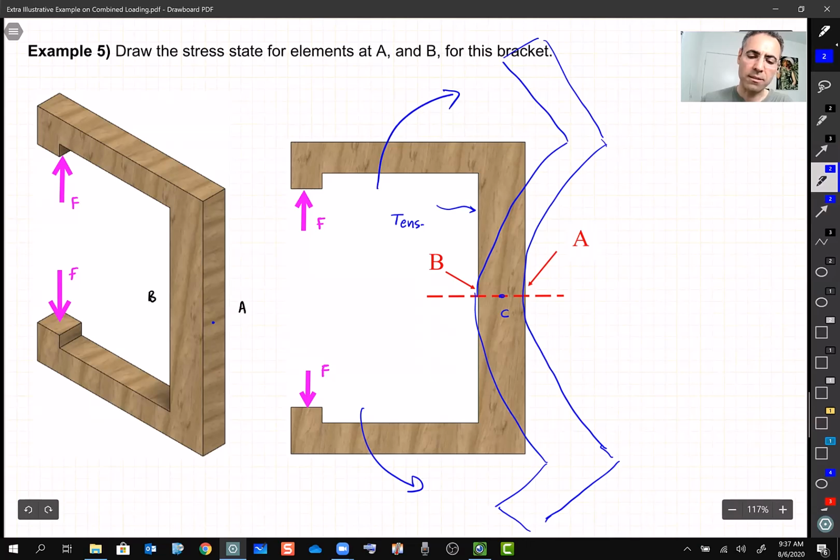Tension, right? You can think of the curved beam that I drew. This side is going to be under tension, and this side is going to be under compression. So that's the first step. If you understand this correctly, then the rest is just simple math. We can figure them out, and it's easy, right? Emily and Thomas were right. If this is going to break, it's going to be point B. But let's see how math is going to solve this problem for us. So far, it's just some simple visualization and exaggeration.